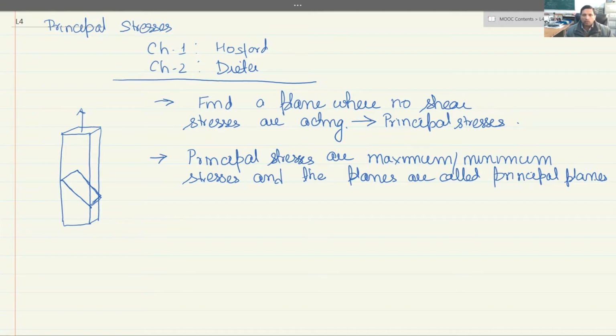The equation you obtain usually involves all 9 stresses, but the same equation can also apply to an element rotated so that only principal stresses are acting, and thus there are only 3 stresses acting on it, giving a much simpler equation for finding the onset of yielding.